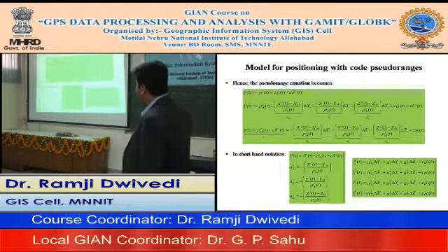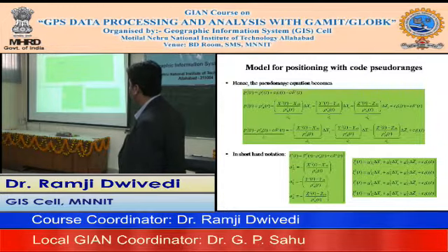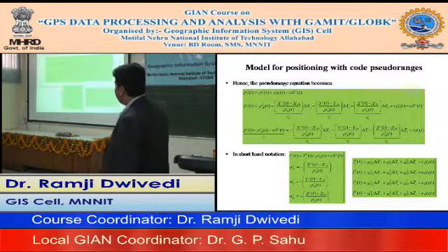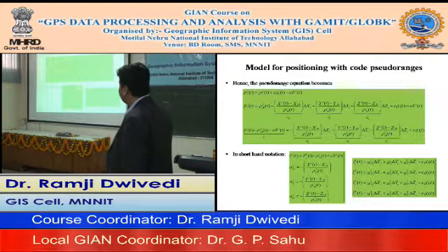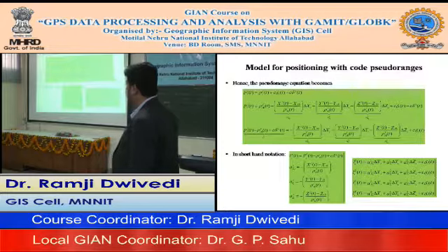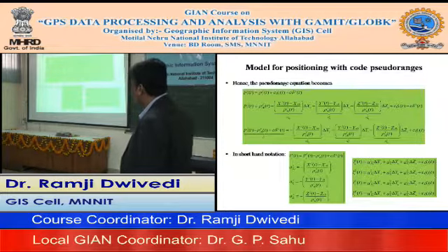This is what we write as L. Now I'll come back to the second part also. Why we are making these notations is that the prime observable L is nothing but the pseudo range and the initial distance measurement with respect to the a priori coordinates, and the clock offset measured from the satellite end. So you could form these equations.